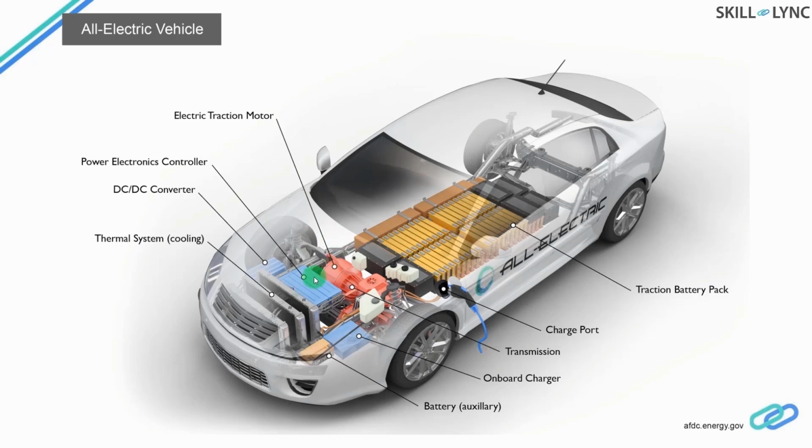Now, in addition to this, electric vehicles have something called a DC-DC converter. The idea is again very simple. You have a lot of power electronics components that are mission critical, and all of them require different DC voltages. So a DC-DC converter is essentially an onboard transformer which converts the voltages to the respective value depending upon the application. And then you have a charge port, which is basically used to charge the onboard batteries. In addition to this, you have a strong cooling system.